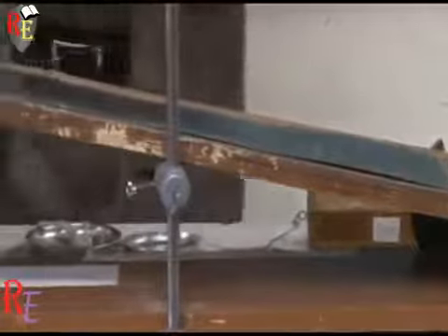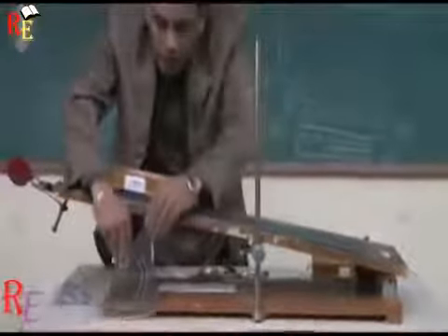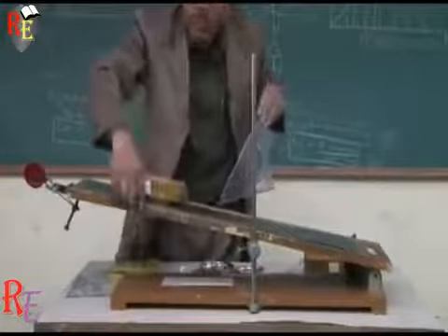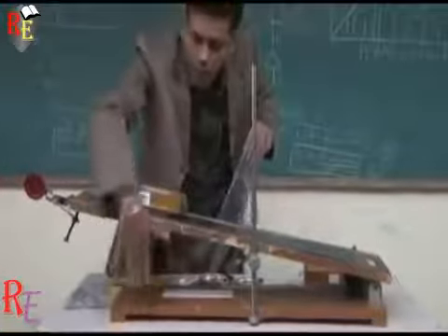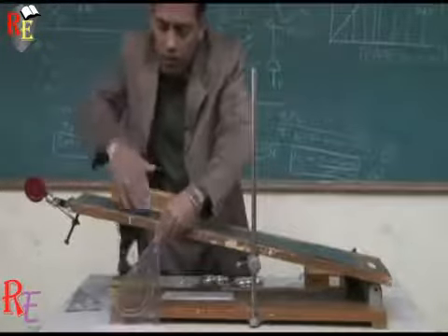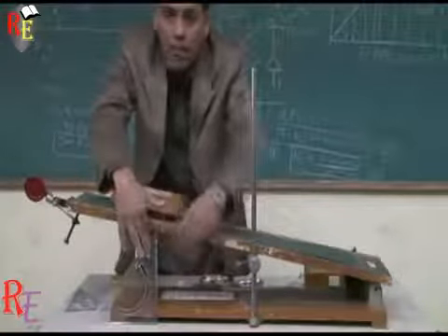The second one is that to measure the angle, I would mark 2 points on this incline. I would determine the height of these 2 points with a common datum.